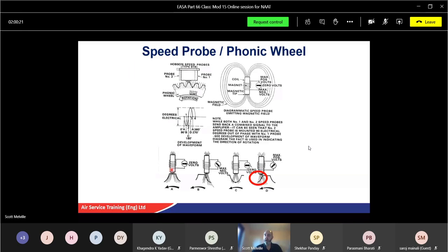You'll start directly off the tooth, 0 volts. It starts to go down the tooth because the tooth is moving away from the sensor, so it will only start seeing some of it. So we get negative, max negative, and then 0 volts. Come back up to max positive, and then finish again on max 0 there, and finish on max positive.